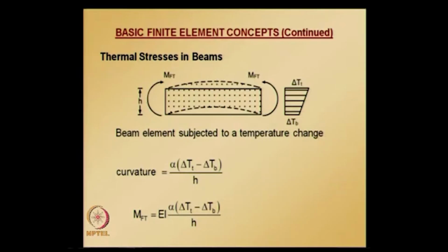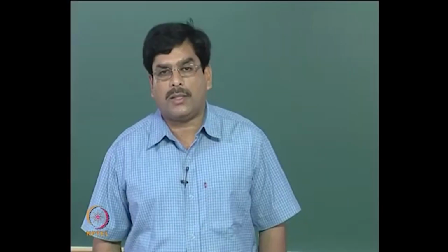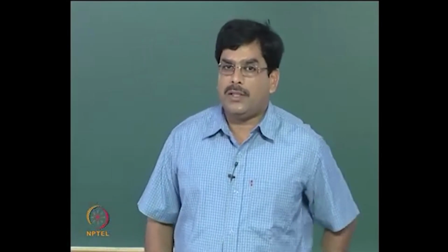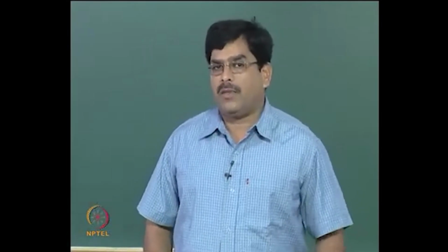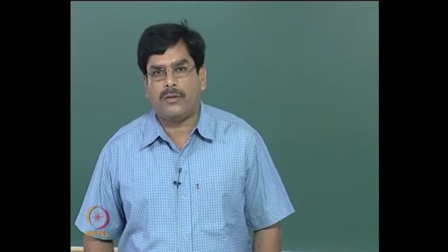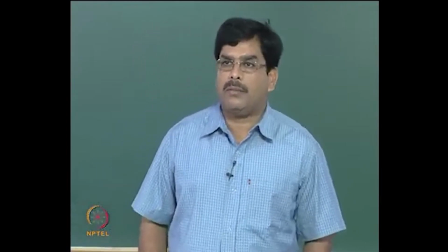Because here the moment is constant, or uniform, along the beam span, instead of a uniformly distributed load we have uniform moment over the length of the beam. So the solution procedure is similar to that we adopted for uniformly distributed load.